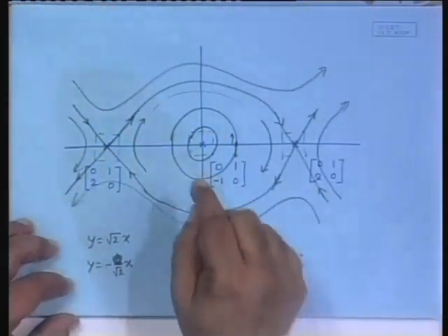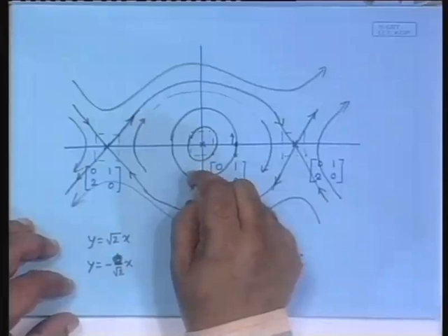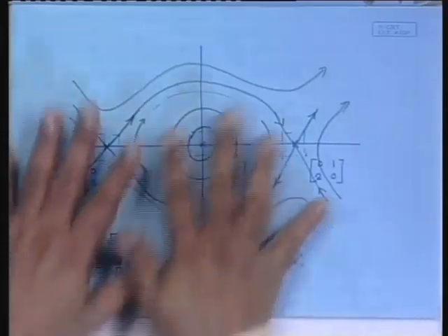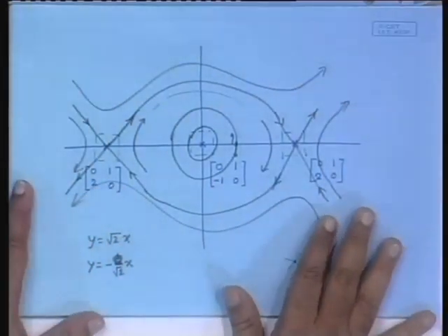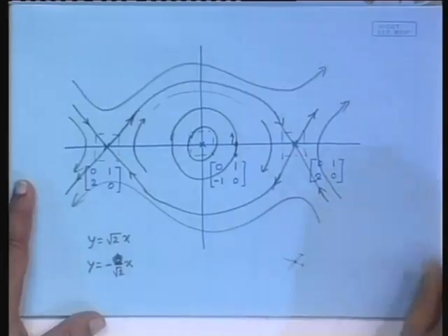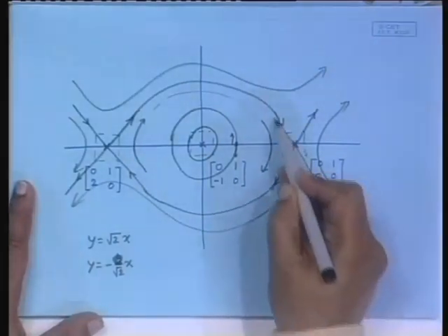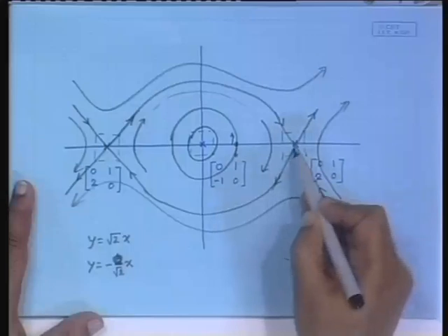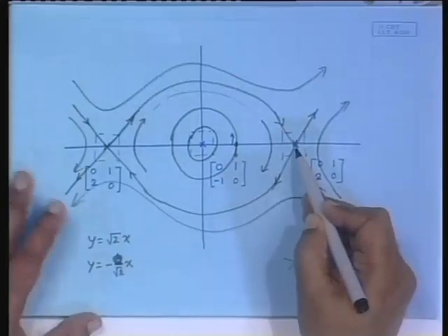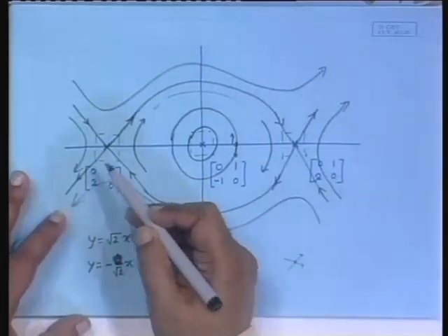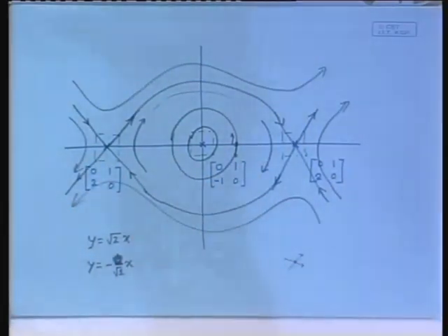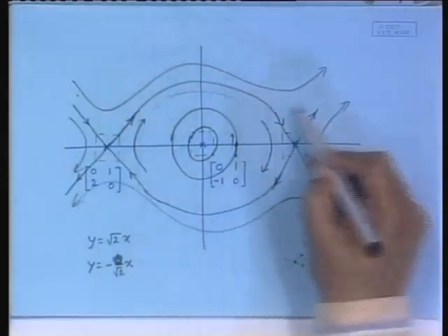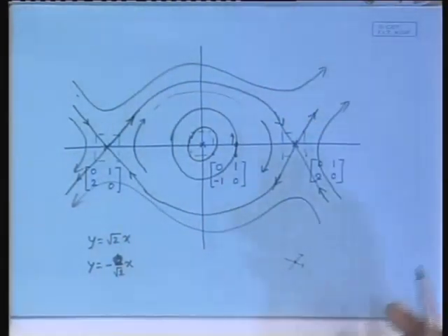By looking at the local linear neighborhood, you have no idea that there are actually very different kinds of dynamics possible in the system. What different kinds? For example, starting within this island, it will always be oscillatory behavior. Anywhere outside this island, it will collapse, it will go to infinity, right. Start from here, it will run to infinity. That means the system will become unstable.